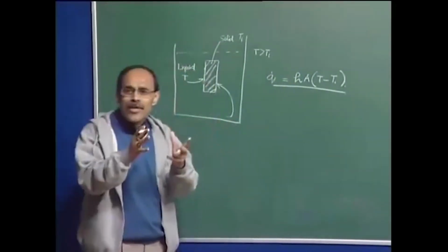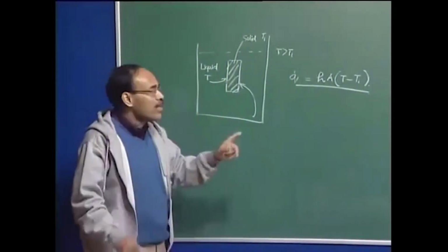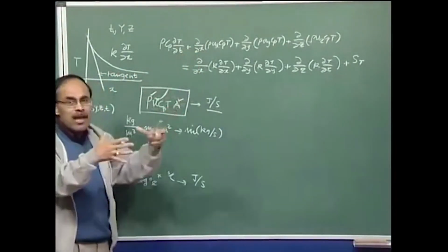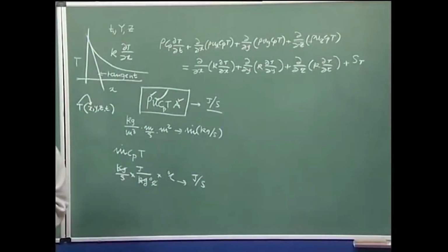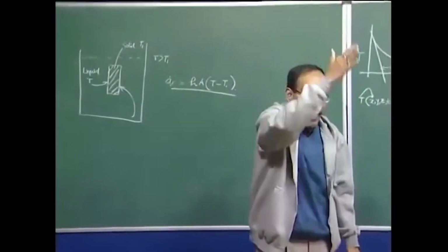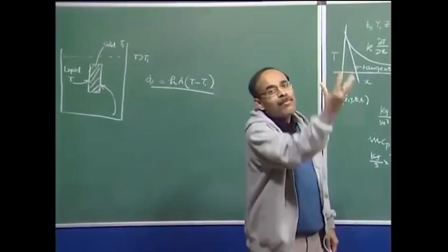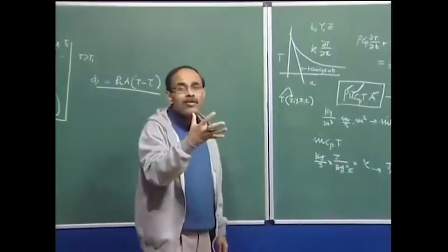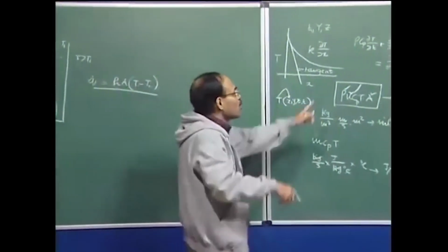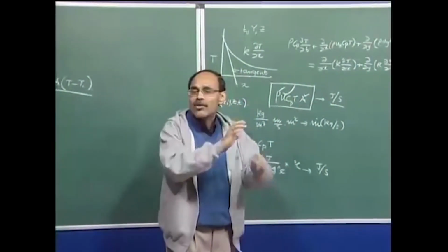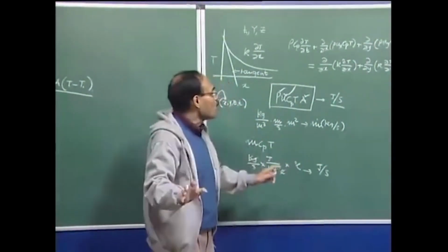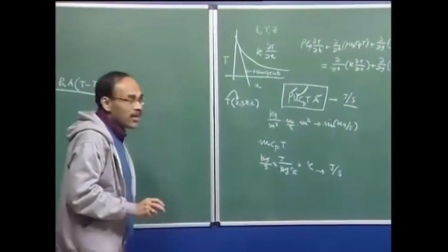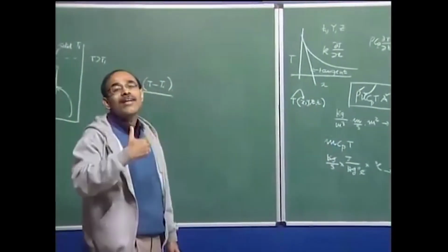Now, for a very simple situation, people have found out that a similarly simple equation can be derived. Simple situation means, say for example, I have a flat vertical plate, and the fluid is flowing past it very nicely in a laminar flow mode, everything is under steady state. In this particular condition one can solve this equation by analytical means. That means I do not have to use any computer or numerical methods, but I can solve it just following the procedure of solving ordinary differential equations, and then I can find out the rate.